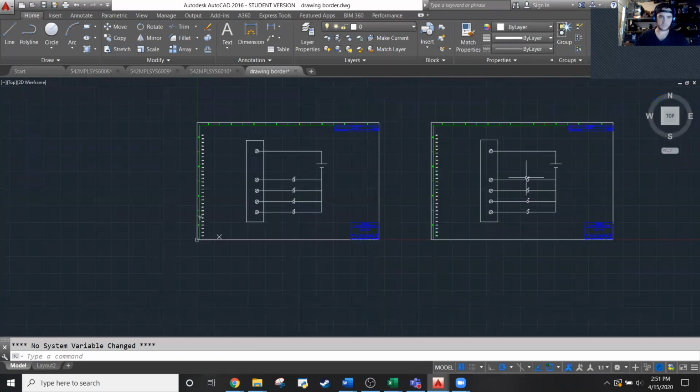Okay. Now, so what if we don't need 30 wires? Do we still have to go all the way to 30 or 29? Yeah, so again, this is going to be your set convention, whoever you're working for. They should have existing drawing sets, right? This might be a panel shop, this might be a site standard, whatever standard you follow is going to be dictated by someone other than you.